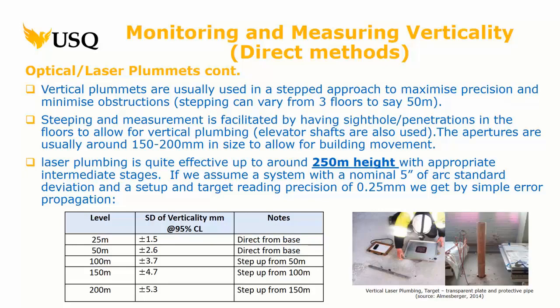Now, the redundant point might be a redundant point of the same methodology, right? Or it could be, and which is preferred, a redundant point using a different methodology, because that then is a blunder check. So we're talking about maybe GNSS, resection using a total station, if it's possible, right? Things of that nature. But this is a fairly accurate method.